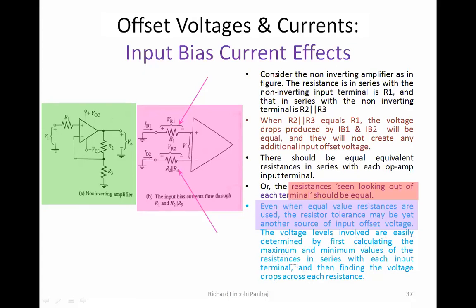So first I will take that tolerance into consideration. Let's say it's about 2 kilo ohms, and the tolerance is probably 0.1. So I will add that 0.1 and it becomes 2.1, and then I will subtract it and it becomes 1.9, right? So 1.9 to 2.1 is my range, right?